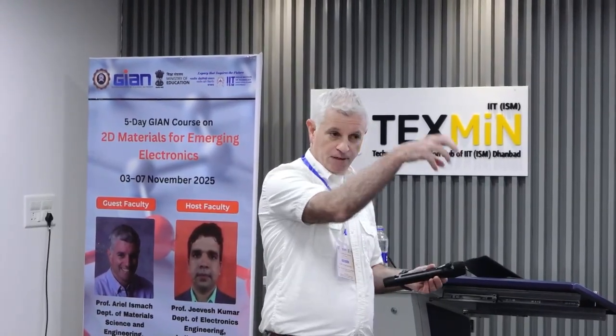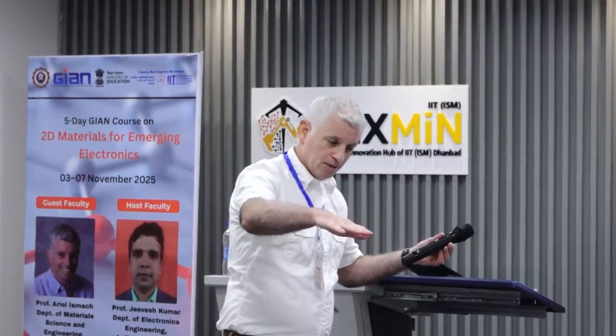It's like the wetting of drops. Are you familiar with that? If the substrate is a high energy substrate, the liquid that you put will usually cover it and have a lower wetting angle. But if the substrate is very low energy, it will not like to cover itself with anything because it's already low energy. Therefore, the wetting angle will be high. So it's the same concept when you deposit thin films.